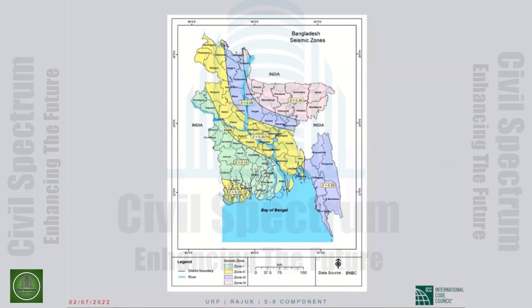Okay, Dr. Ghosh. If a shear wall is constructed as remedial measure for an existing building up to first floor from ground and doesn't continue above, will it be considered as out of plane offset irregularity?